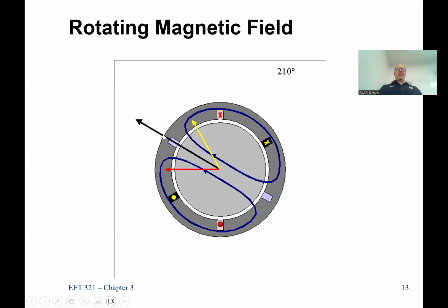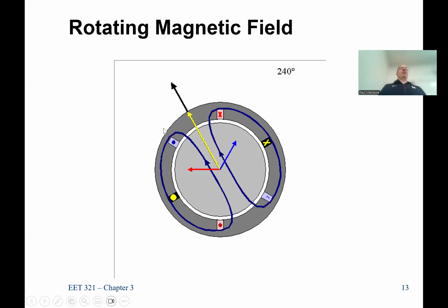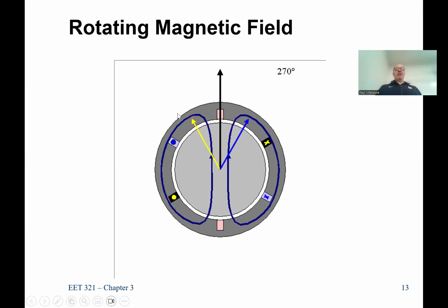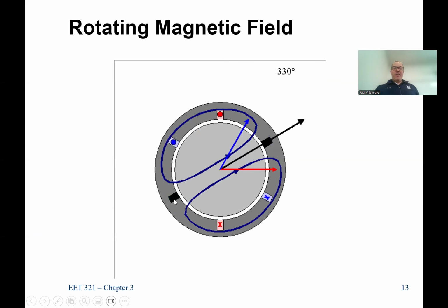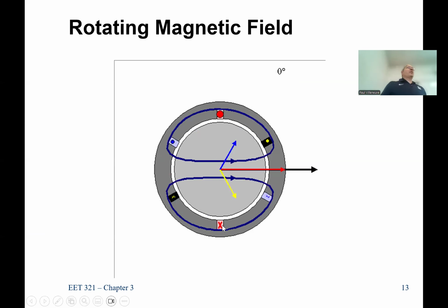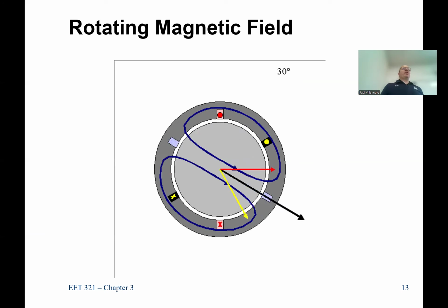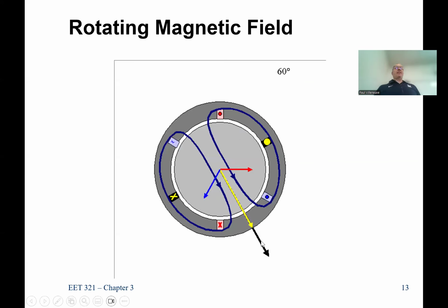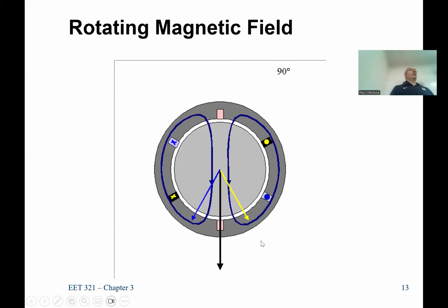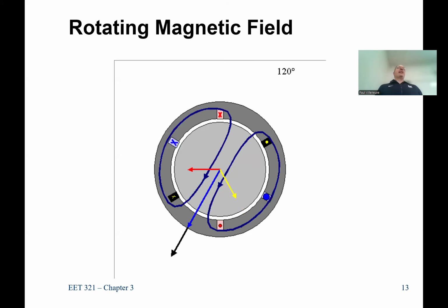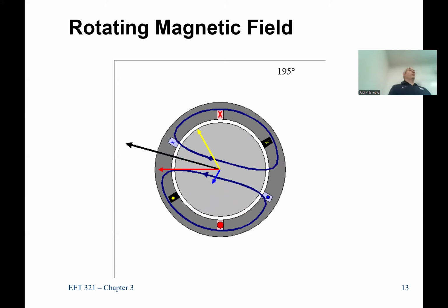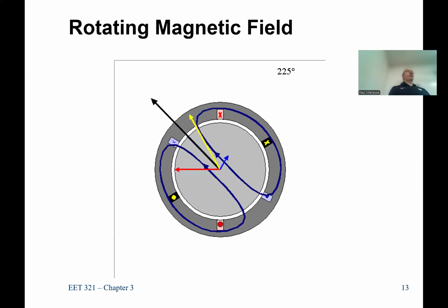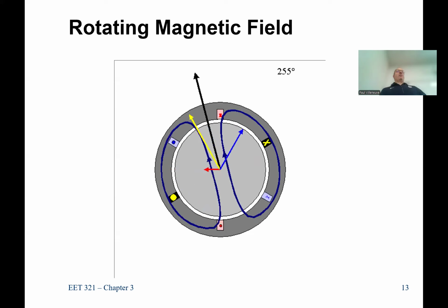What you're trying to get is, I'm building an AC machine, and I want to see if you all understand how those three currents in these windings here, here, and here, going into that machine, are producing a magnetic field that has a constant magnitude and rotates around at a set speed. That's what I'm trying to get. So we did all that math to show you how we get rotation.